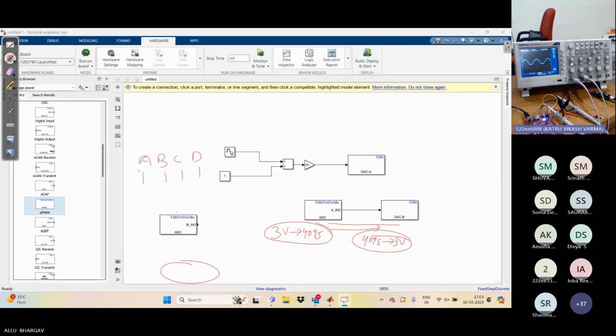Again, if we have above 4 channels, here we are having SOC trigger 0, so we have to give number SOC 1, and we have to wait. If we have 4 ADC channels, now we will be having a delay of 16 nanoseconds here. First this ADC channel will be sampled, then after 16 nanoseconds this channel will be sampled. So there will be a 16 nanosecond delay in the sampling of A and B, so in 1 and 2.